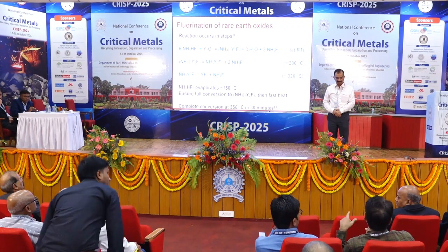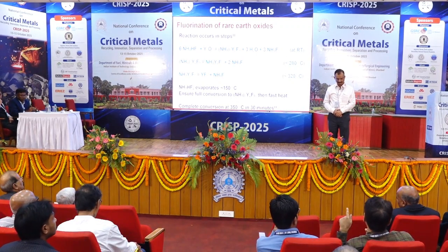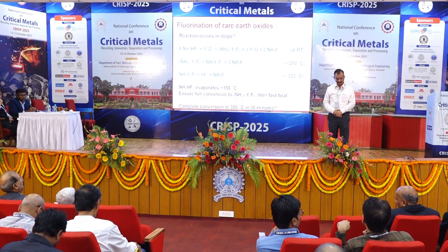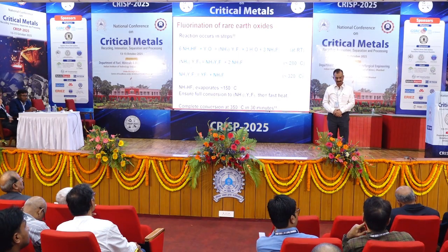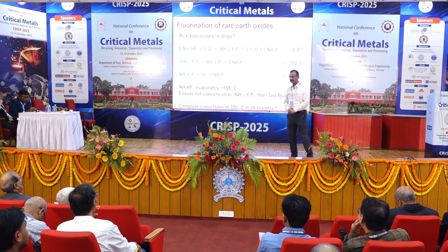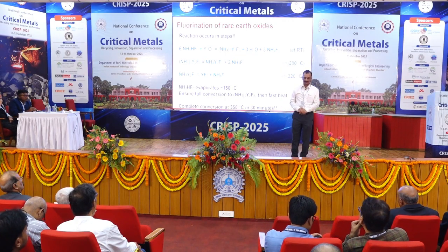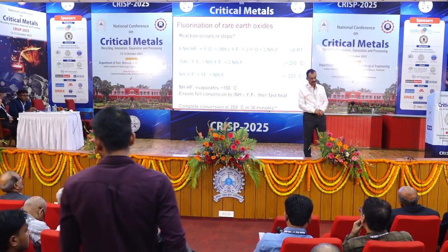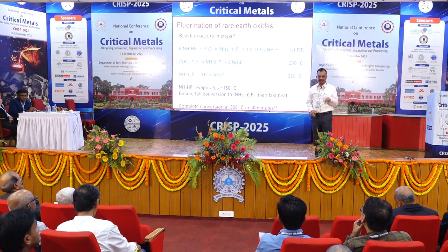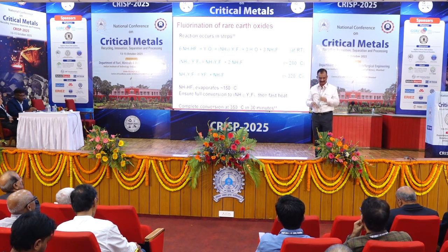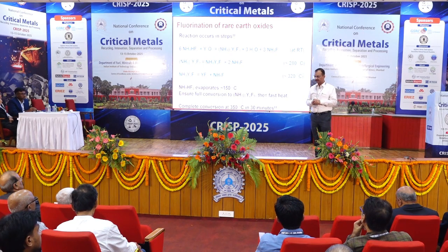Sir, we were talking about pyrometallurgy, niobium oxide and tantalum oxide. Is carbothermic reduction taking place to produce these two? Actually, for niobium, the commercial method is aluminothermic reduction. Although it has recovery issues, carbothermic would be better anyway. But in carbothermy, niobium pentoxide has a problem: it melts and corrodes the containers, and then segregation occurs. So it is not commercialized as I understand, but it can be done.